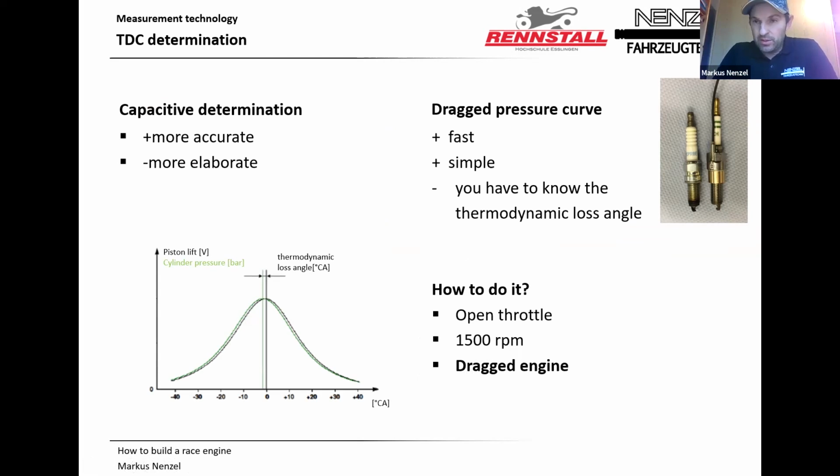It's not so easy, because you can put in a screwdriver and say, okay, there is our top dead center. But if you make a mistake of 4 degrees with your screwdriver, just for a manual test, then this 4 degrees is a mistake for the ignition, for the injection, and for everything. 4 degrees is quite a big gap, because, for example, the 50% burn duration is, from the books, 8 or 9 degrees, and there you have a mistake of 4.